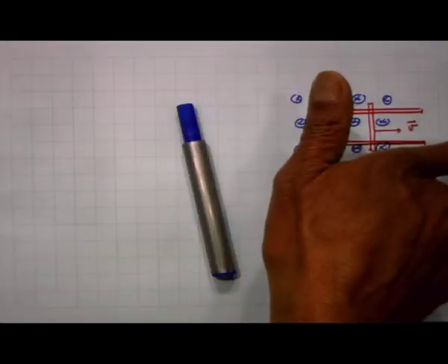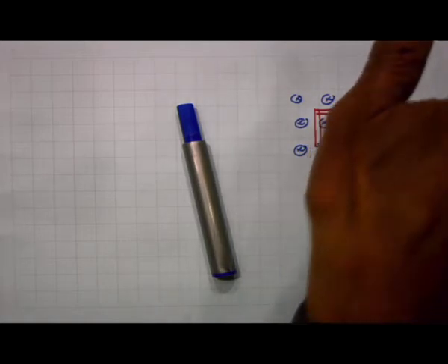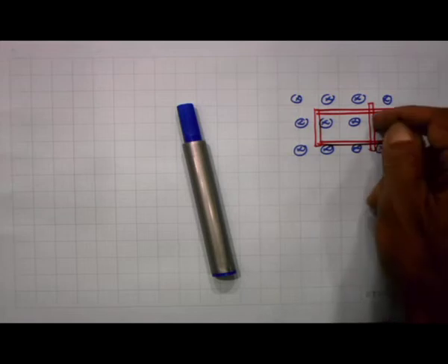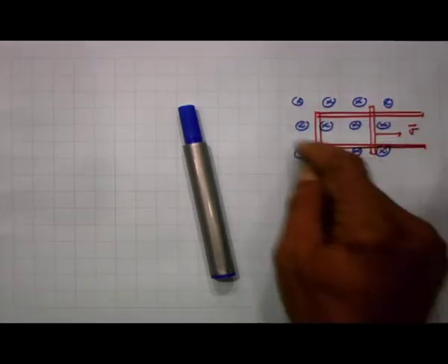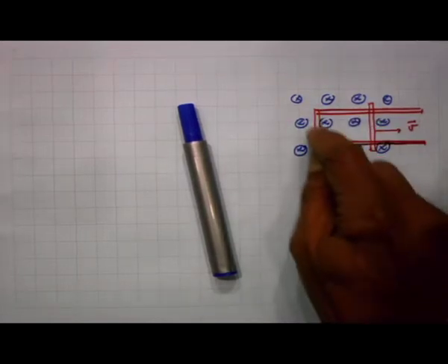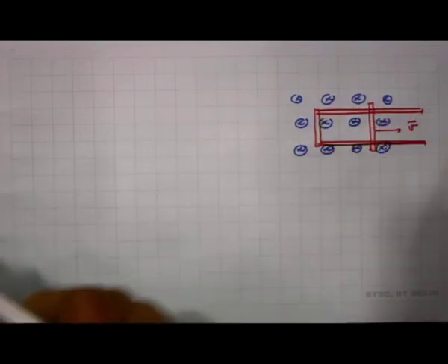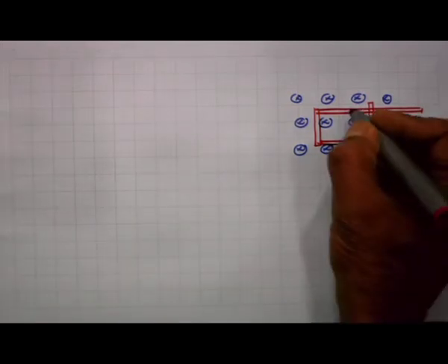Because the velocity is in this direction and the magnetic field is pointing downward, the v cross B is upward; because the electrons have a negative charge, they are pushed down, and the electrons then follow this path, and so there is a current generated. The electrons are flowing in this clockwise direction, so that leads to a current in the anti-clockwise direction. So, there is an induced EMF leading to a current in this direction as shown here.